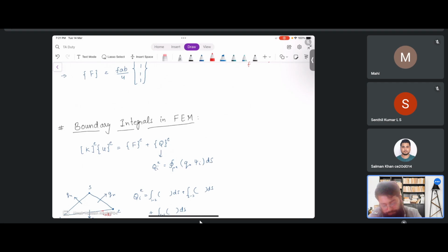If you remember, when we break down our weak form and write it in terms of interpolation functions, we get a matrix term K times our unknown variable, and on the right hand side we have some body force term we may or may not have, and we may or may not have a boundary integral term. When we do integration by parts, we get a boundary integral term.